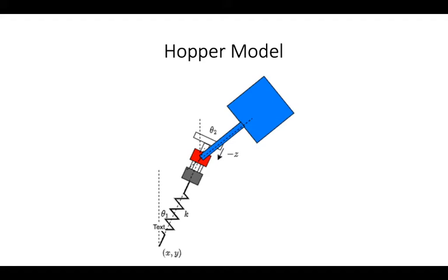spring in the leg. I chose to model contact forces as springs in order to soften the stiff dynamics. While not the most accurate, this assumption meant that I could define the contact forces in the dynamics equations rather than make the contact forces decision variables in the optimization problem, which I found to work better.